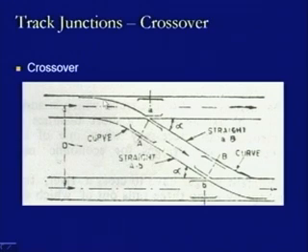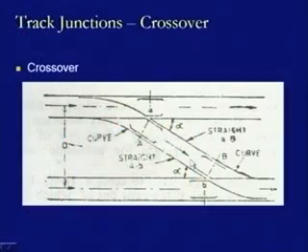So, we have a curve provided at this location, then there is a straight portion in between, and again there is a curve, but the curvatures are opposite to each other, and that is why it is a reverse curve condition with a straight portion in between. So, this is one curve in this curvature, this is another curve in opposite curvature with a straight portion in between. This is the design of a reverse curve, and these straight lengths can be computed based on the angle of crossing, that is alpha, because the tracks are parallel to each other.